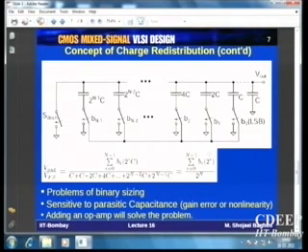So now the problem is it is very sensitive to parasitic capacitances that exist at the output, right? So this creates a lot of problems. Therefore, we add an op-amp so that we can make this node a virtual ground. And then we put a capacitor in the feedback path of the op-amp. And therefore, we will get better control of the effect of parasitic capacitance because all of them will be connected to a virtual ground.